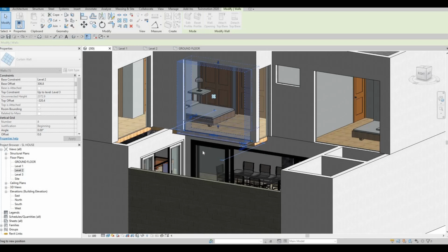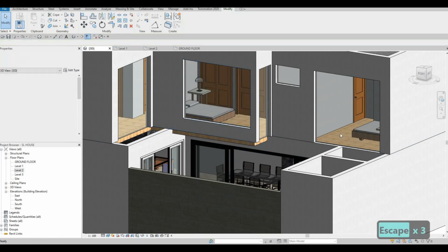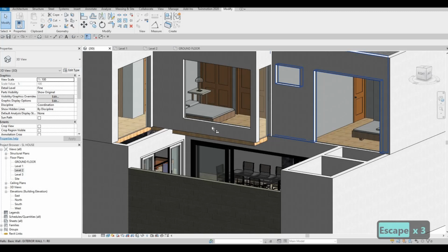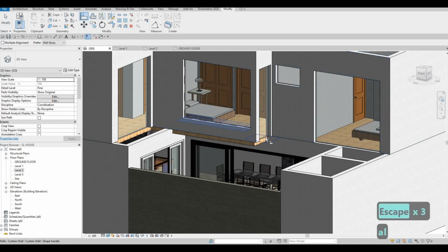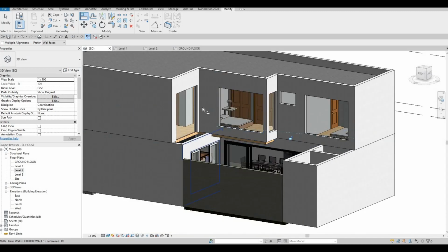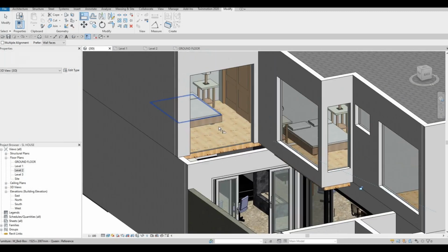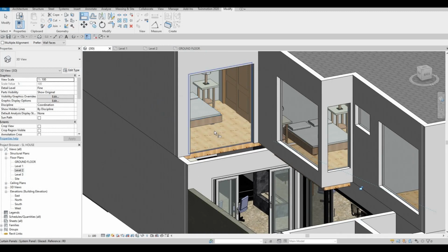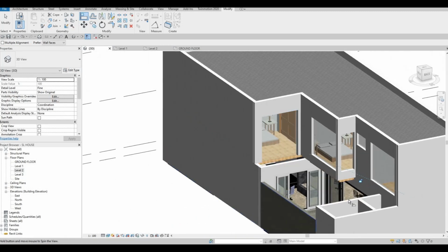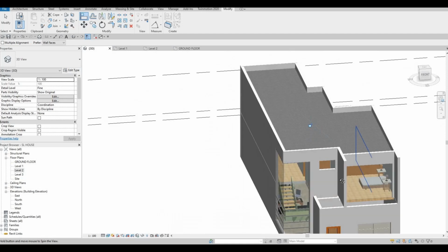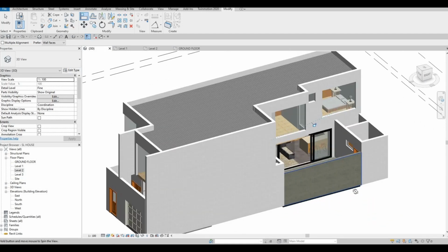We have a curtain wall, but it doesn't have a balcony, so we're gonna set a height for that. So probably that height, and the same goes right here, align. So they could be the same height. This will be just below because we need to add a glass door right there. So I'm just setting this up.